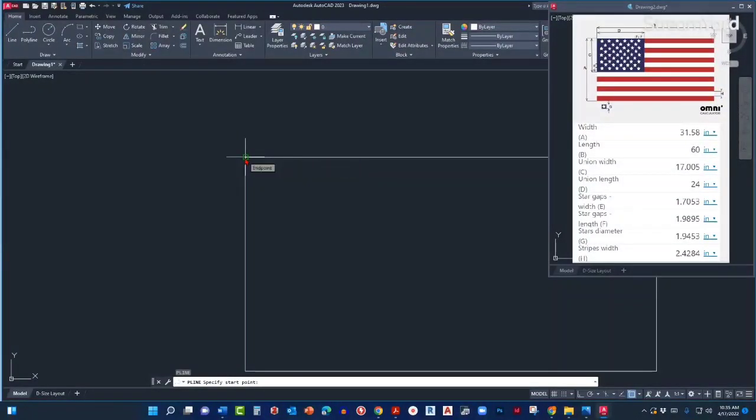So now I can simply click and start drawing my polyline, right? But I'm going to need another precision setting to start my polyline at a certain distance. Over here we need the distance of C in this case. So what I'm going to do is cancel that. To cancel or finish any command, you can use the escape key on your keyboard, like so.